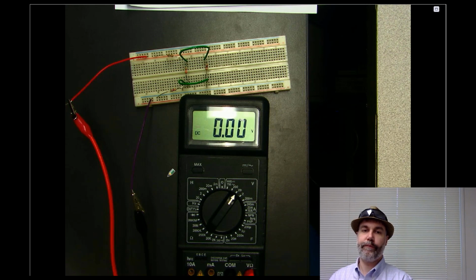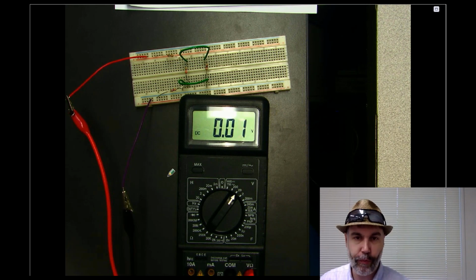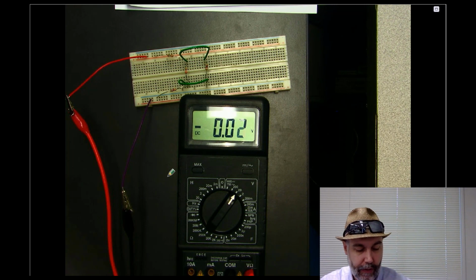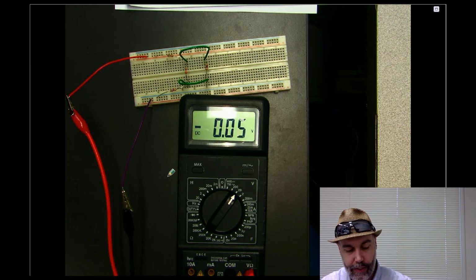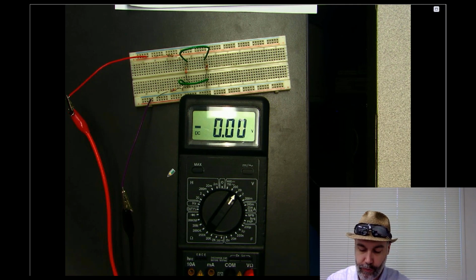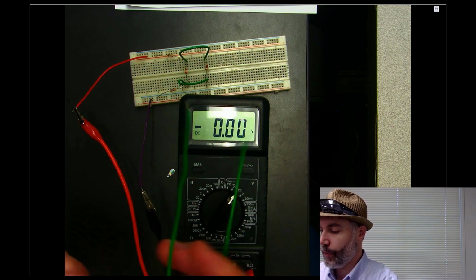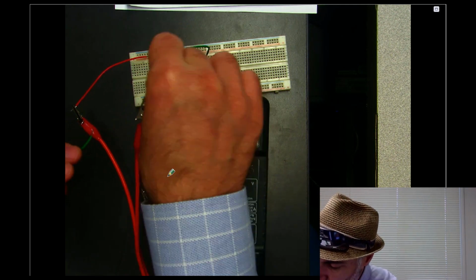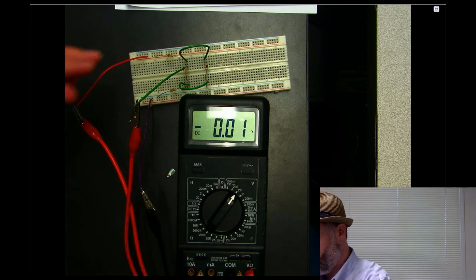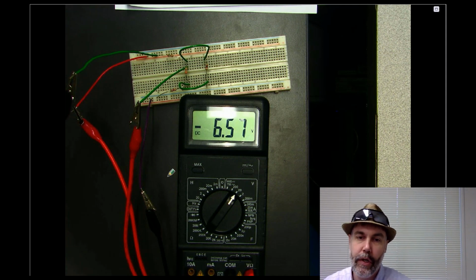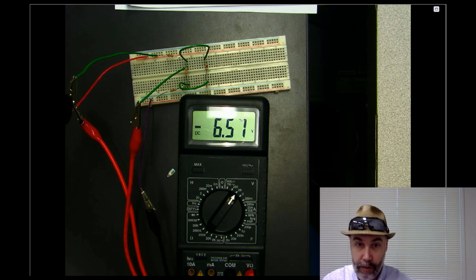All right, and then in order to measure voltage, I'm just going to attach the meter to the two ends of each resistor. Now, I could clip directly onto those two ends of the resistor, but I don't like to do that because that has a tendency to pull the resistor out of the board. So what I do instead is I just grab onto two jumper wires, and then I plug them into the same rows as the ends of those resistors. So for this first resistor, I'm going to plug the leads in there. So that gives me 6.57 volts.